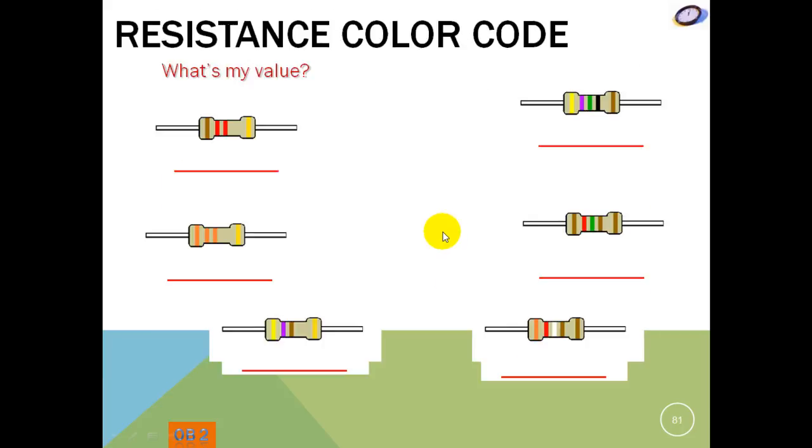And then we did a little exercise that calculated the values by looking at the colors. Sometimes you need a magnifying glass to help you determine these colors. But for those who use these color-coded resistors every day, they get used to what they are and can easily pull them out of a bin. For those of us who don't use them that often, it takes a little time, and of course to verify that you read the colors right, you test it with an ohm meter.